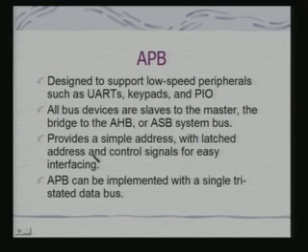It provides a simple address with latched address and control signals for easy interfacing. An APB can be implemented with a single tri-stated data bus. So, it is very similar to the kind of bus which you encountered with the 8085 or 86 family. It also has the latched address and control signals. So, it is a very simple, straightforward bus.